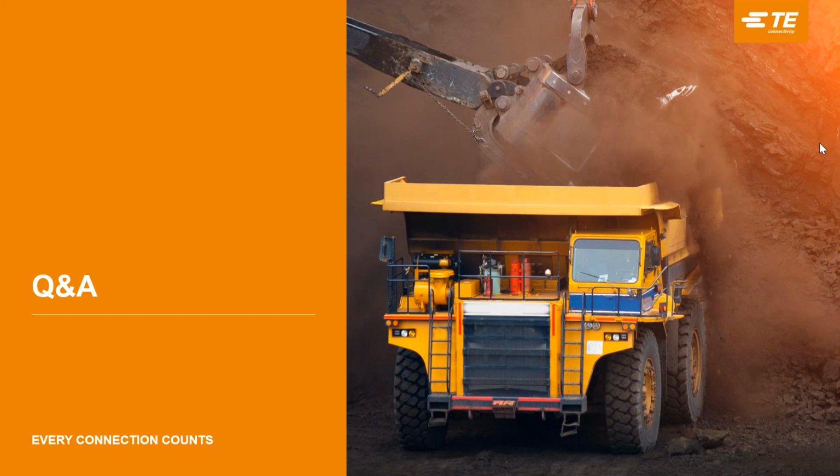Paul? That's a very good question. So if you look at a traditional pin and socket type of connection versus, let's say, the suggestion of a USB connector, which is basically a plated flat terminal either on a printed circuit board, and then it's generally a single point of contact on the mating contact itself to provide the connection. So for a connection on your PC, for example, to plug in a USB or to charge your cell phone in your automobile, that works perfectly fine.